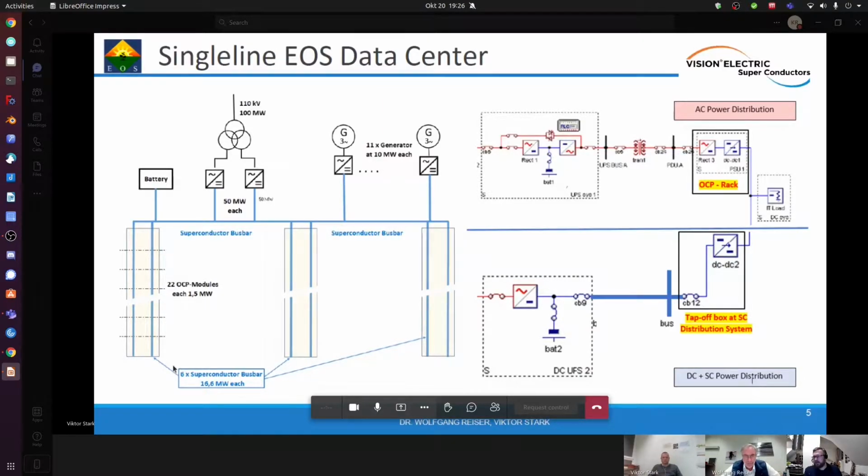Let me rephrase this, because you mentioned a lot of very good points. Traditional DC supplies in data centers usually have a big problem because we have data halls about 200 meters long, or even a little longer, so from the start of the hall to the end you would have a massive voltage drop, right?